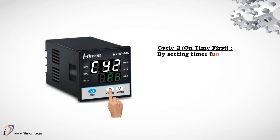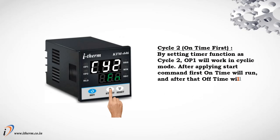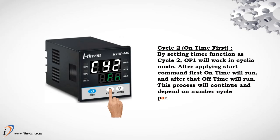Cycle 2. On time first. By setting the timer function as cycle 2, output 1 will work in cyclic mode. After applying the start command, first on time will run, and after that off time will run. This process will continue and depends on the number cycle parameter in the user list.